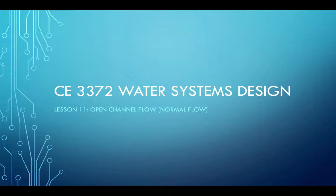Rapidly varied flow is flow that changed its behavior over a relatively short distance. The classic example of that is flow going from supercritical to subcritical, transitioning through a hydraulic phenomenon known as a hydraulic jump, and you've got to create that in the fluid mechanics lab, no doubt, and you've seen them in your day-to-day lives, whether you know it or not.